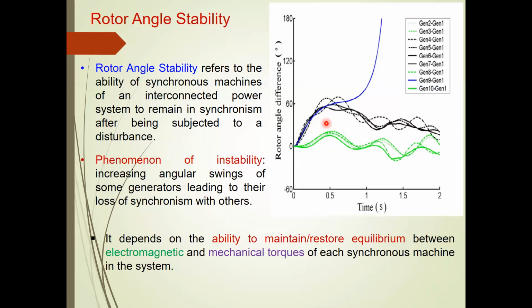That is also possible. And in some cases, it is also possible that they may swing at a different phase angle shift, because when you look at this, this generator has the peak at this time duration, while this one is lagging behind. So this generator reaches its peak at this time period, meaning the peak of the first swing of this generator is lagging behind this one. That is always possible when you have several generators in the system. Following the disturbance, the dynamics of some group of generators could be similar for a certain duration, and then in the following time period their behavior could be a little different. Thus it is very important to analyze the generator dynamics following any disturbance, right?